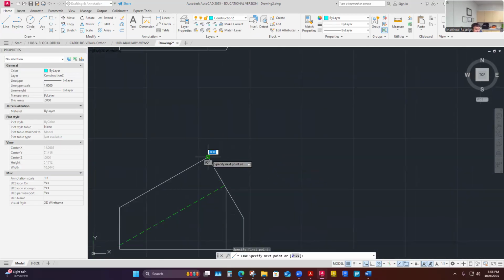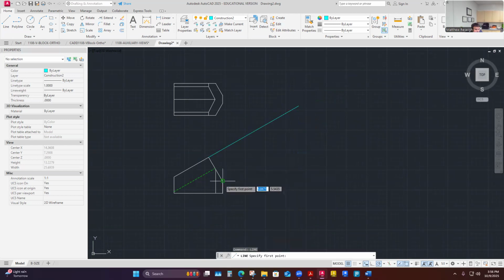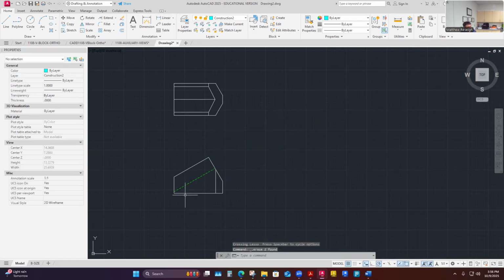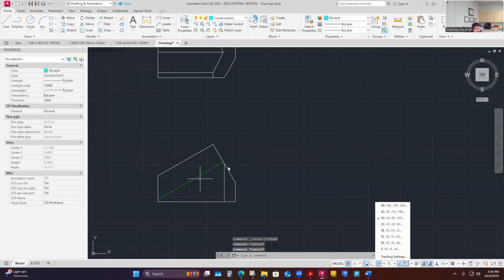So what I'm looking to do is just to build this plane out here, right? Like if it was 30 degrees perfectly, yes, it would be this plane out here. I'm going to build this little boundary area where it lives. I'm just going to be careful, as I don't know if I can snap to that. I've got kind of a weird dimension, 0.10, 0.57. It seems like it's made something that's not, it's 90.04. So I don't know if I can use my object snaps or my polar snap tracking. Technically it should, because it tells me it's 30 degrees over, and so I should be able to just come back the difference of that and project off it.